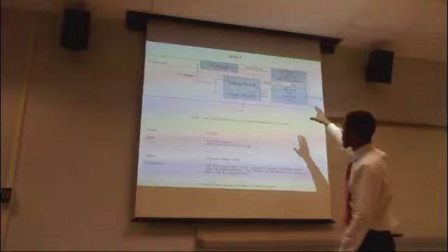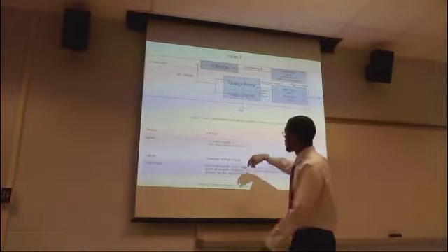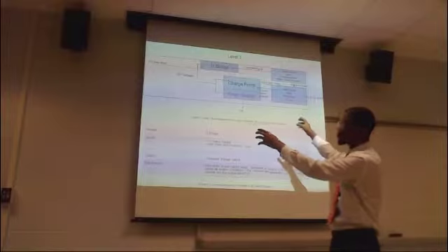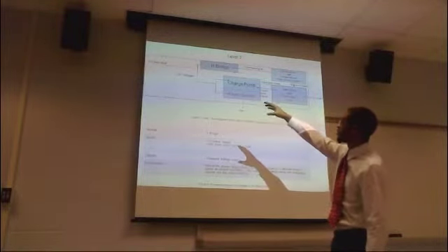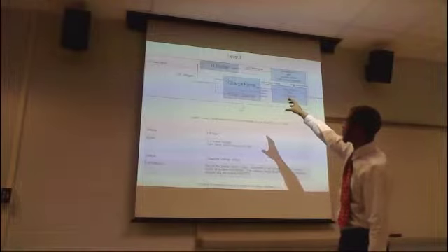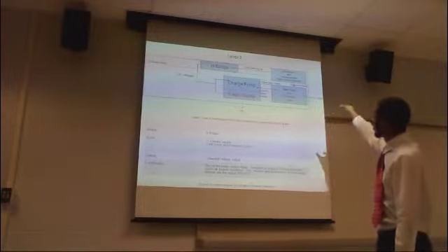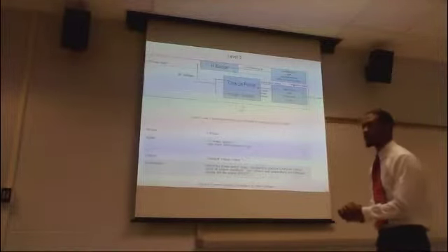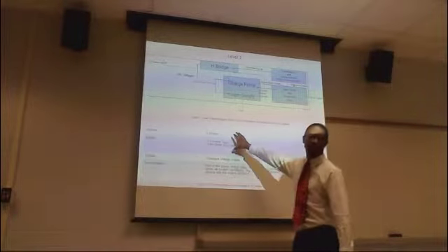The PowerPoint kind of made the lines really messed up. But basically, what's going on inside the motor controller itself is there are multiple different types of components. From the input, you see power supply entering into our H-bridge, our charge pump, and our logic supply, which are controlled from our power regulators and our protection logic.